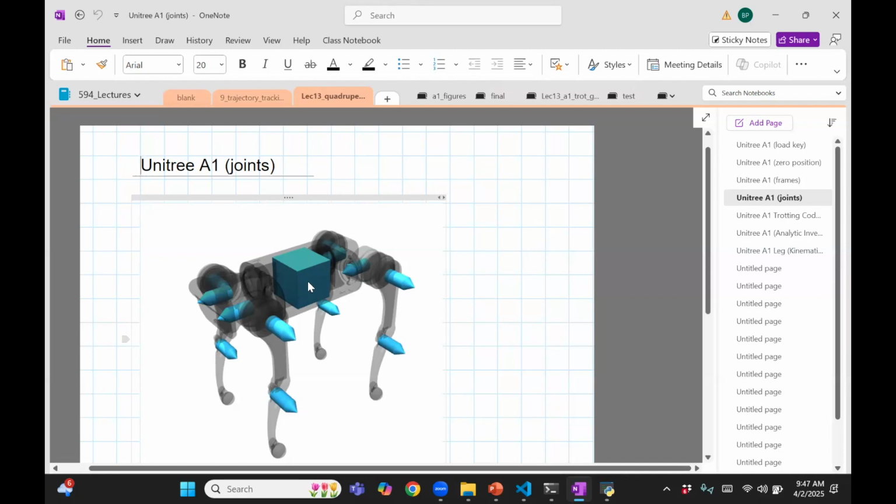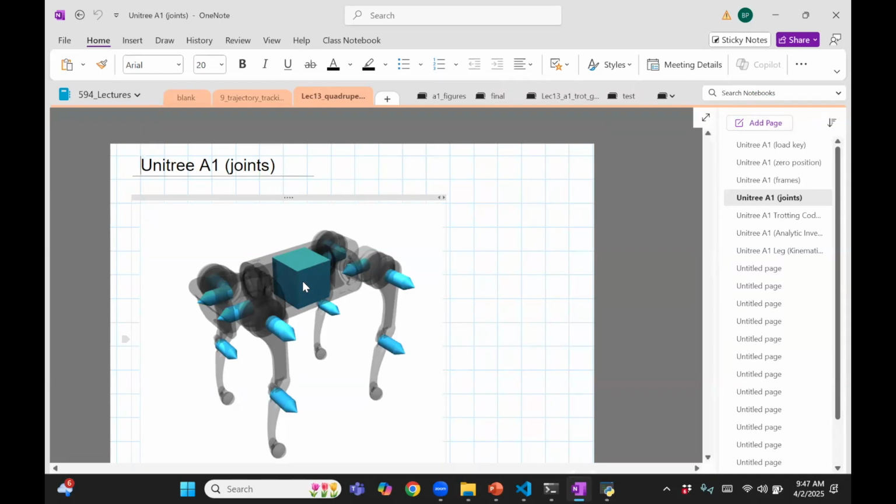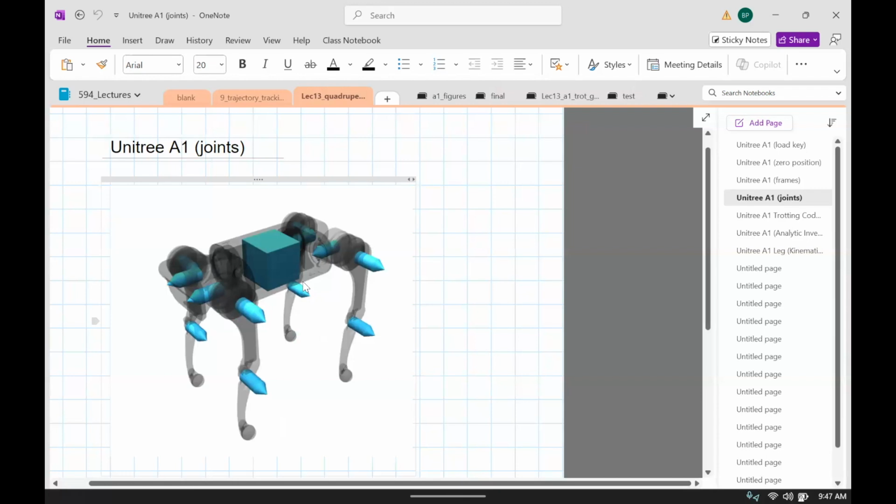Okay, so actually it's modeled as a free joint. A free joint has 6 degrees of freedom, position 3 and orientation 3. However, when MuJoCo writes this down, it actually uses quaternions, because we've seen quaternions are a good way of representing robot configuration.